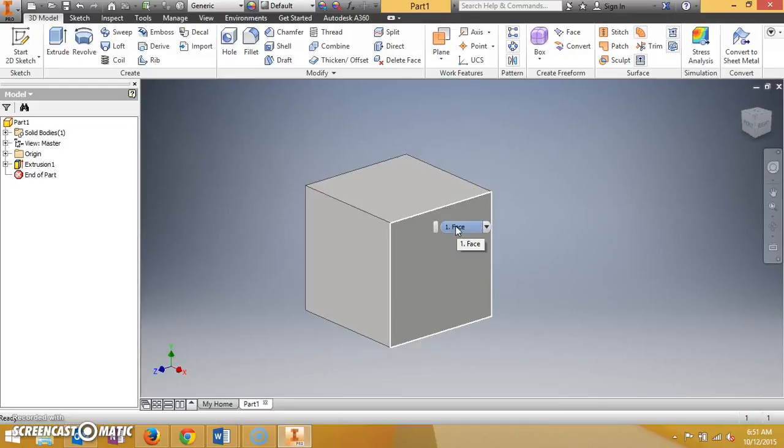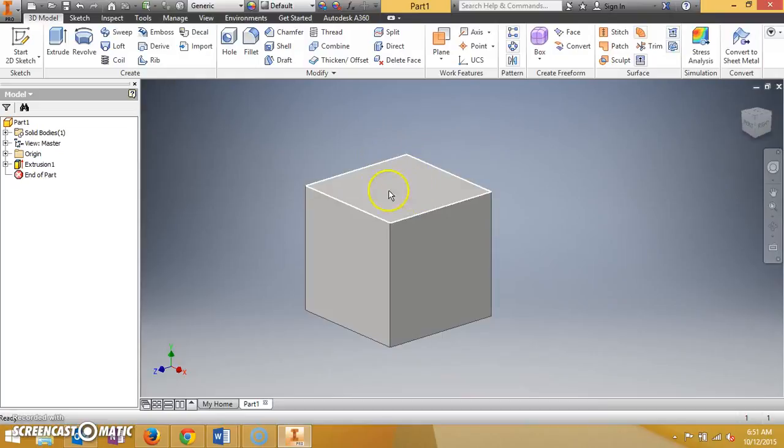Now it's just a plain cube. We kind of want to spice it up just a little bit. So what I'm going to do here on the top is bring another smaller three-dimensional square, and I'm going to bring it up and out from the top. To do that, I'm going to select, left click the square, and you'll see it gives me these 3 little buttons. I could change the extrusion, I could edit the sketch, or I could create a sketch on top of that particular surface.